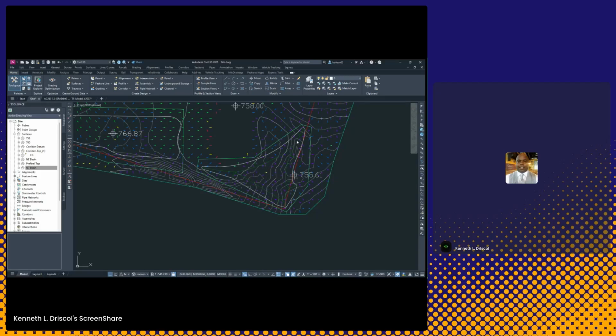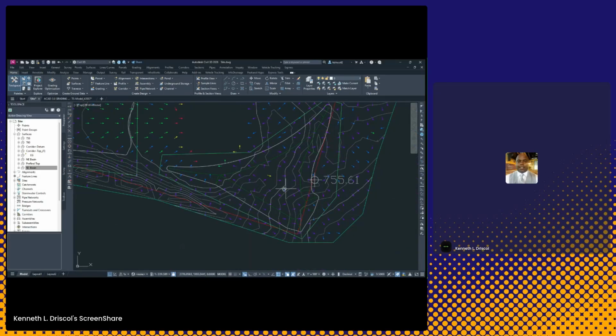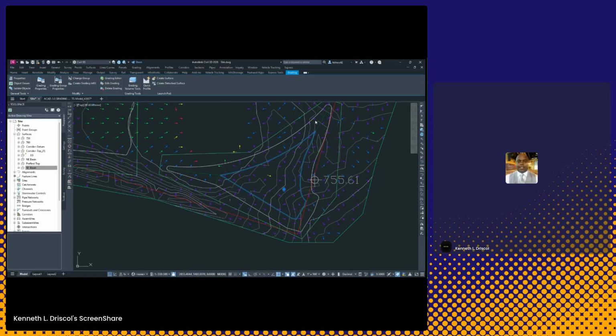I also want to be able to create an infill. From this, you can see this little triangle right here. And if I pick on it and go in and select 1, the elevation editor, or 2, the grading editor, I have functionality that will give me specific properties. So if I go into grading group properties, it's showing me that this is a grading group and the information, and I need to target the surface.